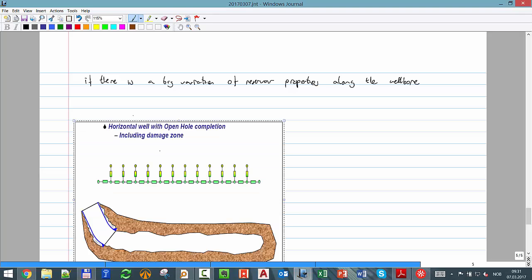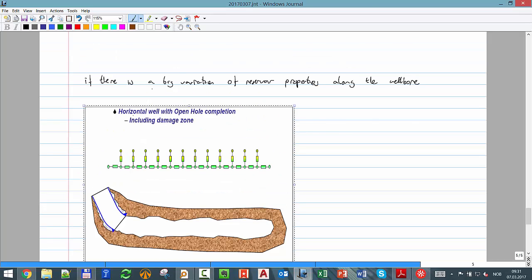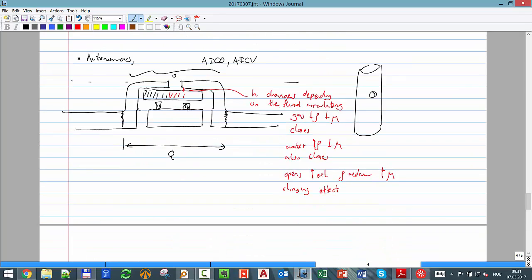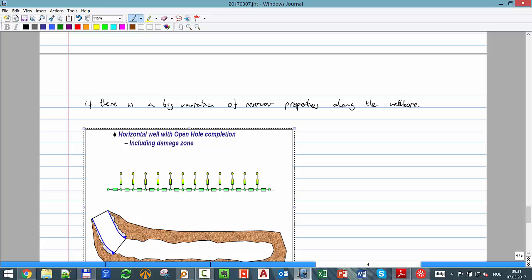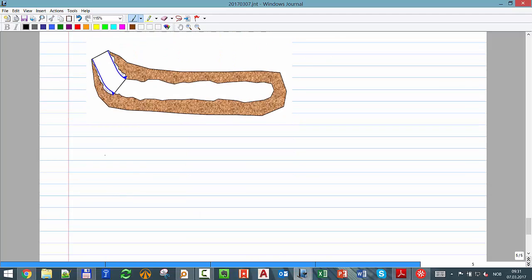Okay, then in that case, for example, there is a big change in permeability. I just split into sections that I assume have constant permeability. But we can have downhole networks. We solve them the same way. We assume a rate or we assume a pressure, and we try to converge that. In this case, I will have a bunch of junctions, so I have to make sure that in each junction I have mass conservation and pressure conservation. You probably will get an exercise to practice. Okay, so we close that part.